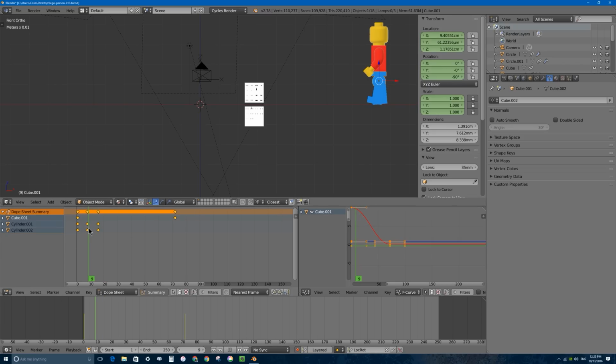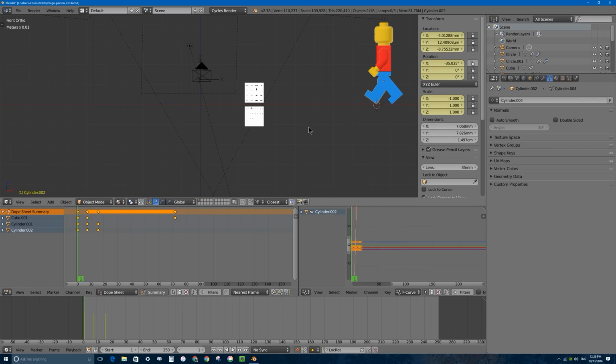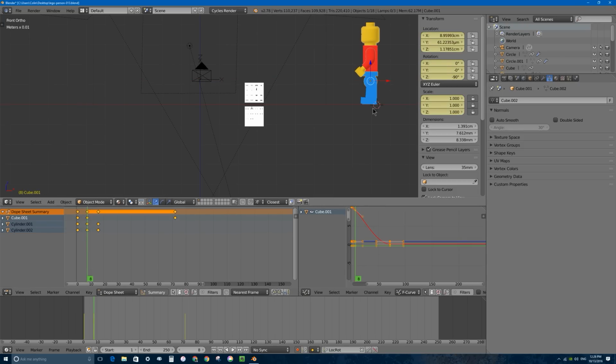Let's go ahead and look back at where that planted leg was just a moment ago. If I look at this first keyframe at frame 1, this is the planted heel. That's where the weight is going, and that heel should stay in the same spot until it's no longer the planted leg, until this leg takes on the weight of the character. So if I scrub through to frame 8, well, wait a sec, that heel was there, now it's sliding back like he's walking on ice. So at this frame, I'm going to have to make a position for this hips piece, and I'm going to move it forward so that the heel of that weight-bearing leg stays in the same position. So it needs to be right about there, so that that weight-bearing leg won't be sliding around.